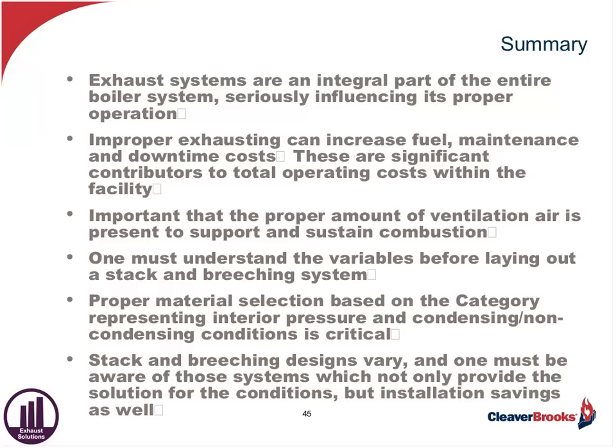If you get into a situation where you've got a lot of variances, as I mentioned before, caused by downdrafts or wind velocities or ambient temperatures, whatever it might be, then it may be prudent to take that step and invest in an induced draft system or an automatic dampering system. But if you've got pretty good assurance that the conditions are fairly stable, then it's just a matter of properly calculating the breeching and stack diameters and lengths in order to accommodate the proper draft. My counsel is don't spend anything you don't have to.